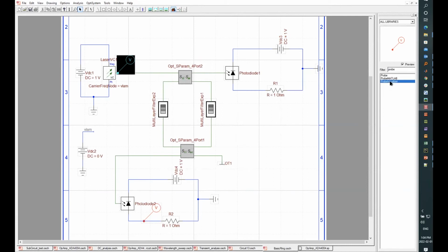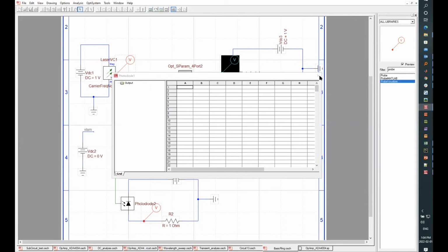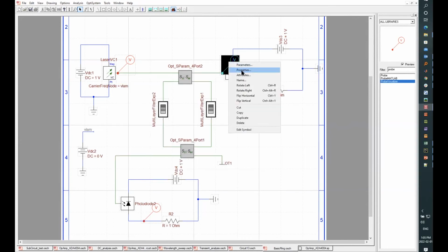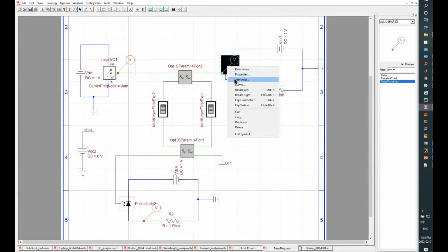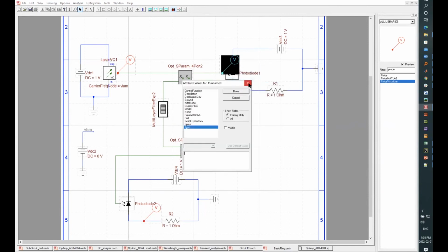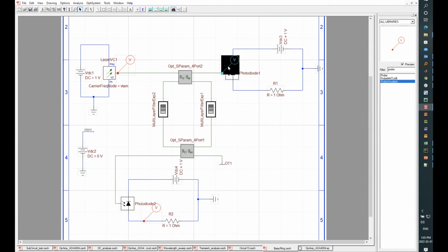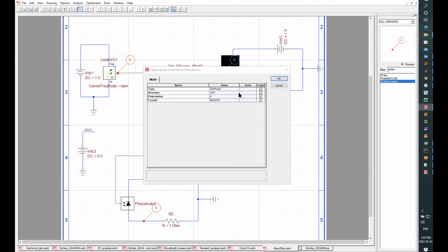I think the plot that just popped up did show the units in watts, so that does answer my question. It also allows you to see multiple wavelengths. If you have more than one laser generating different wavelengths, you can plot them in the same graph as well. Right now nothing will show because we haven't run the simulation. The way we deal with multi-channel simulations is by keeping them in different signals. You can think of it as having a bus: each optical connection between two devices represents a bus. We have a series of optical signals going one way, and each signal represents a different wavelength. And then we also have signals going the opposite way. Nice.